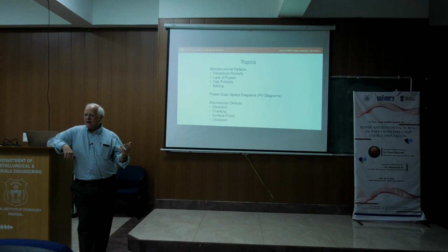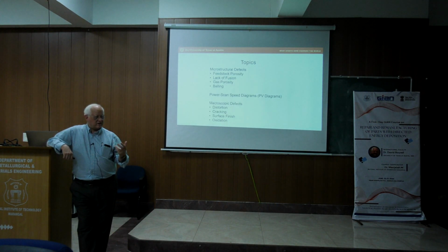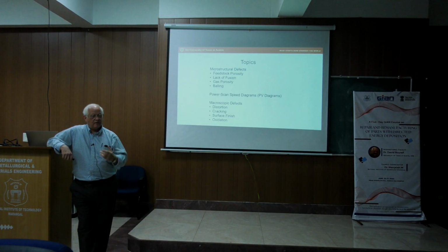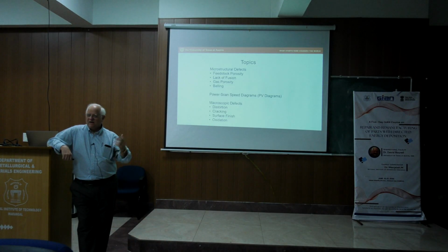It turns out that the powder, whether it's for DED or for powder bed, because of the nature of the way it's manufactured, typically it's atomized. Powder is what we typically use in additive manufacturing. It turns out that powder actually has porosity in it, and some fraction of that porosity remains in the final part, maybe 10–20%.